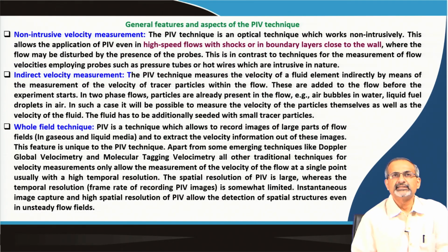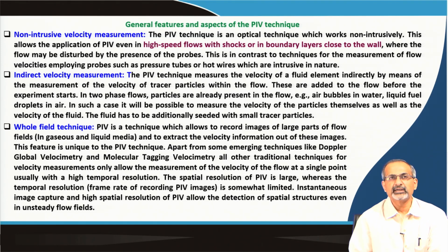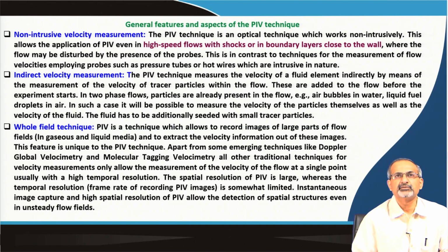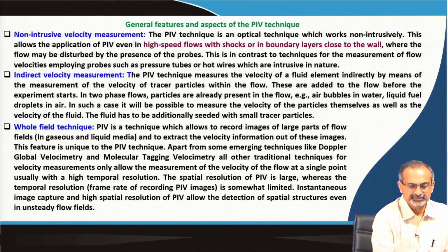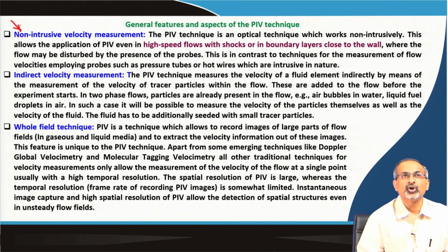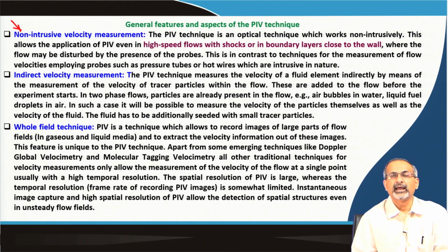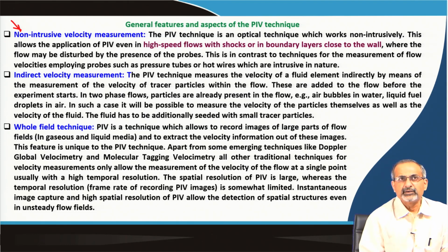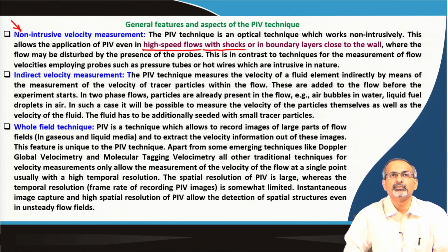Let us look at some of the general features and aspects of PIV technique, which we have already started discussing in the last few slides, but we are re-emphasizing them once again. As we said earlier, it's a non-intrusive velocity measurement, and it works extremely well in certain situations like high speed flows which have shocks, because if you want to put in a probe, a measurement instrumentation in any high speed flow, it acts as an obstruction to the flow. It would immediately produce shocks and it will disturb the flow altogether.